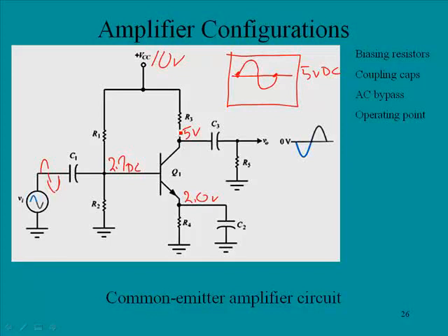And the reason that I chose 5 volts here is that it represents what we call an operating point. Sometimes they call it the quiescent operating point. The reason for this is that this value allows for the maximum signal change. Notice the power supply is 10 volts, so realistically it can't go that high, but at least in theory the signal could go up to 10 volts and it could go down as low as 0, because those are the 2 reference points here, 0 and 10 volts. So this would optimize the passage of signal. Now when you get into the real analysis, you'll find that we would not be able to go to 10 or to 0, but placing the operating point in the middle gives us the ability to get the most signal swing as possible.